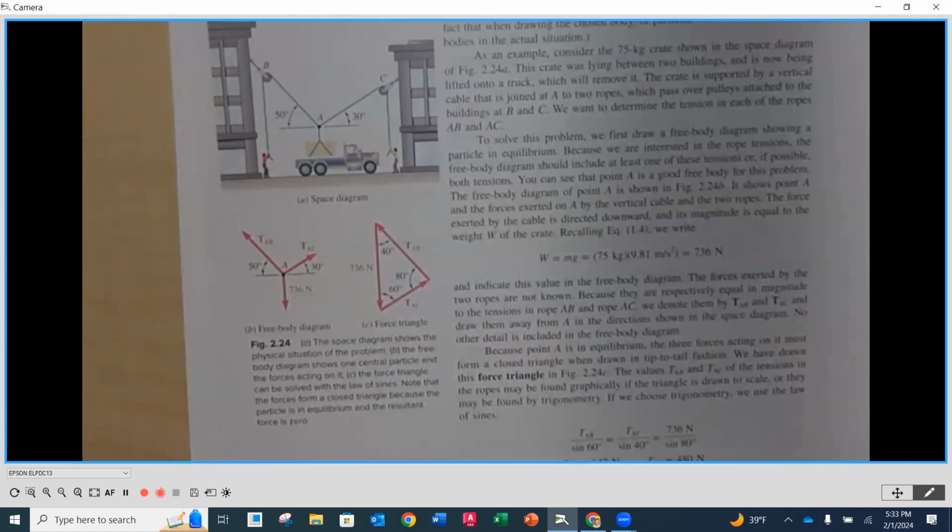We've probably exceeded the weight limit, but what do they have in place there so that's not a problem? Do you know what that's called? They call it a safety factor. When an elevator, for instance, is designed, they design it not for the capacity that's posted in the elevator, but probably for about 5 to 8 times more than what is posted, so that in the event it does go over, there's not going to be a problem. So here, if this goes over the capacity, they're also going to think about, okay, what is the safety factor?